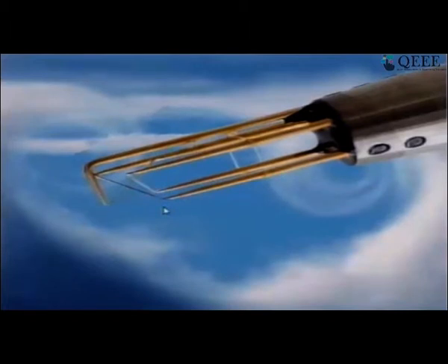This is a hot wire, and like this you have 3 wires which are mutually perpendicular to each other. And what this probe does is that when you put it in the flow, you get a measurement. The wires are very, very thin, of the order of 5 micrometers in diameter. The human hair is about 100 micrometers. So they are very, very thin. How we make it is quite an interesting thing. And this is a basic tool that one uses to make point-wise measurements of velocity and turbulence in an airflow. So all the data that I was talking about of how mean flow changes and how boundary layers are developed, one used this in the case of gases.